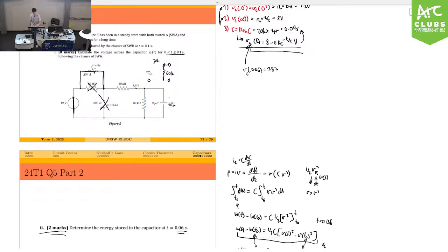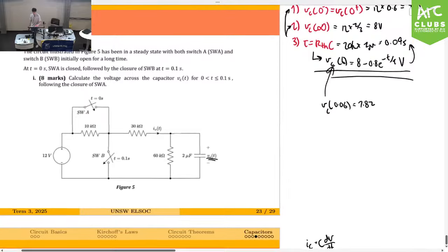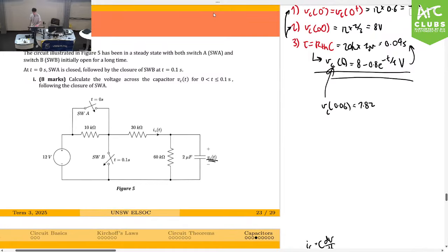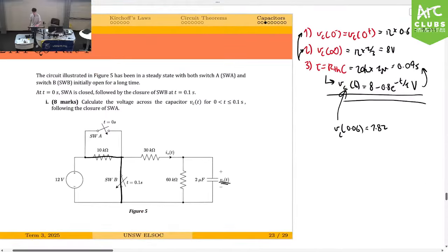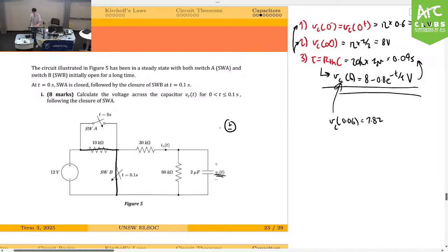So for this question, here's a couple things that you want to keep in mind. The first thing is that this has already been shorted. You're not going to be flipping the switch back open. So this becomes shorted. Now this also becomes shorted. Now, I don't really like this question because what you've done is that you've shorted your voltage source, which shouldn't happen in reality. This is a past paper question as well, which is pretty disappointing. But hopefully you recognize why this is wrong.